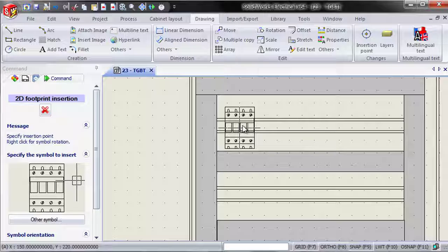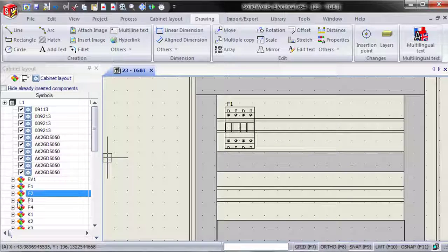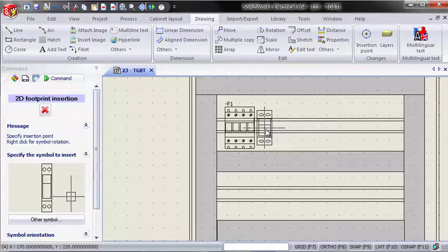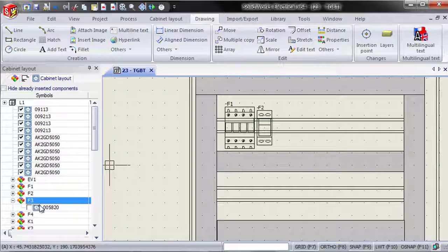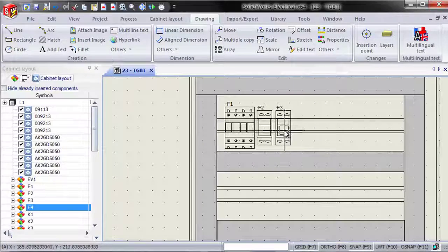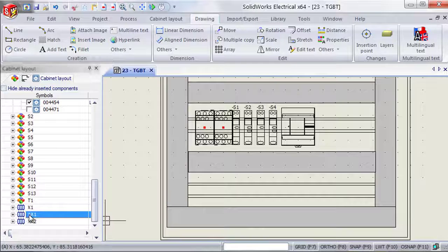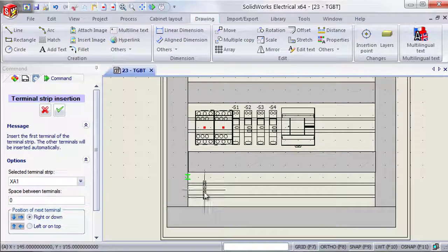All of the shape information is automatically generated after we select the manufacturer part in the schematic diagram. By doing the panel layout, we could get direct measurements of the layout for its components, so it will make sure the dimensions of the box panel are enough for all of the components.